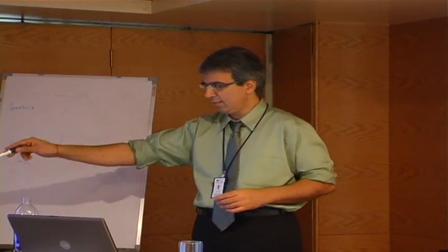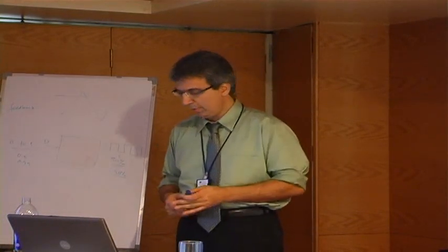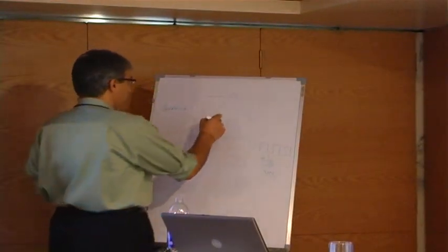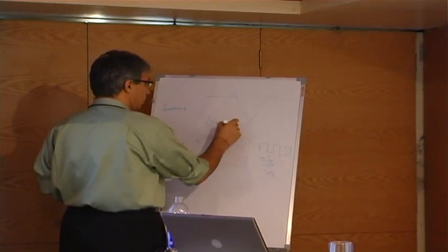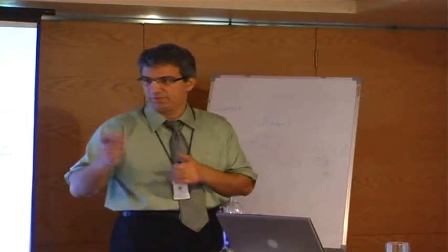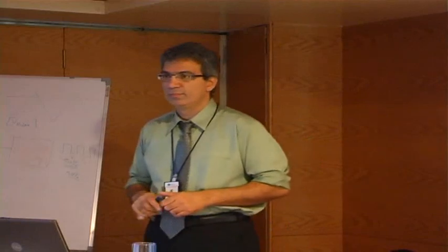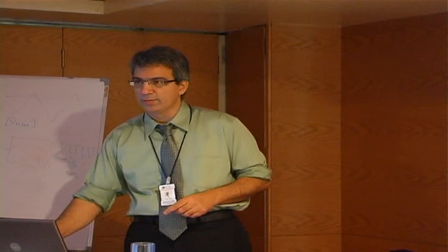One way to do it is I have a feedback signal and a triangular waveform, and as a matter of fact you can generate the triangular waveform using the V-pulse source, which we have used for back EMF and for gate logic. So that's definitely one way to implement that portion of the system. I think that's a very valid point.